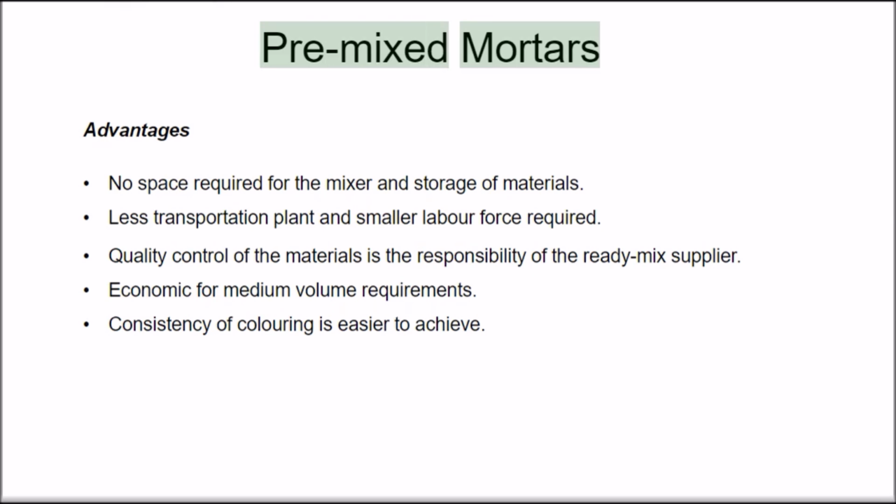Pre-mixed mortars. Advantages: no space required for the mixer and storage of materials. Less transportation plant and smaller labor force required. Quality control of the materials is the responsibility of the ready-mix supplier. Economic for medium volume requirements. Consistency of coloring is easier to achieve.